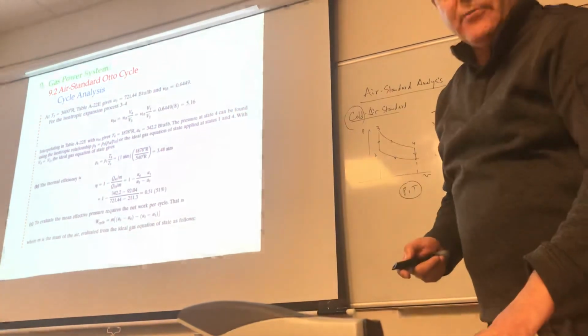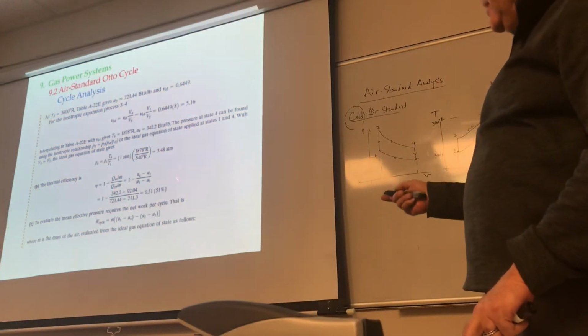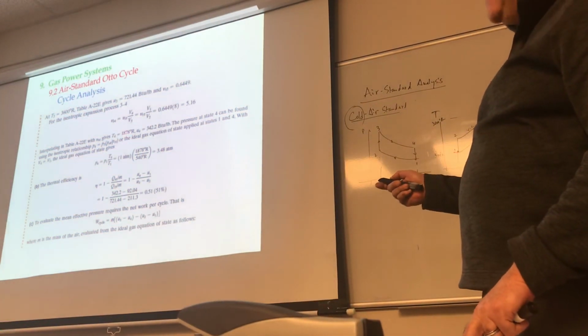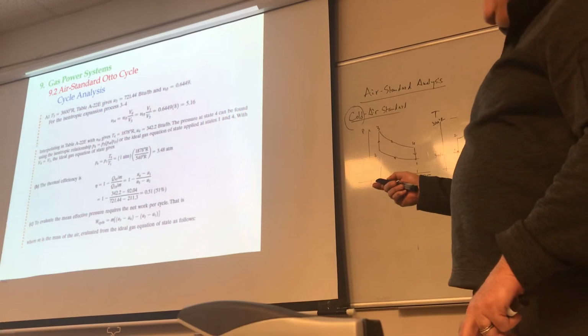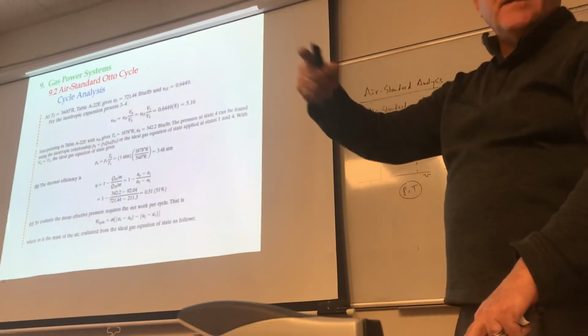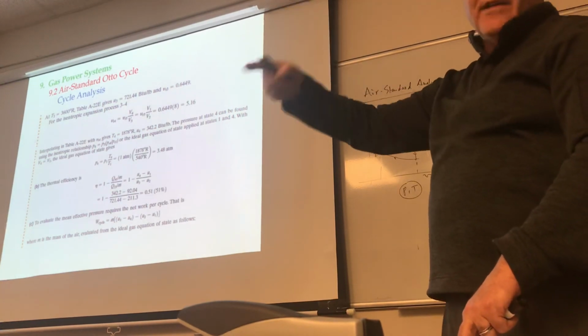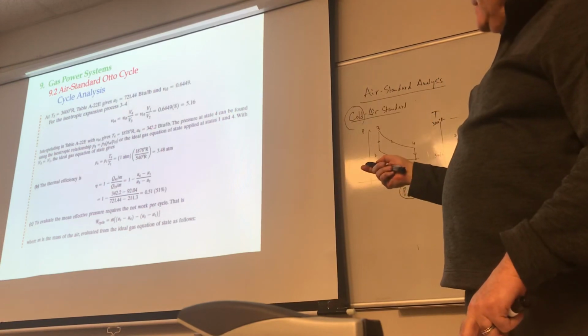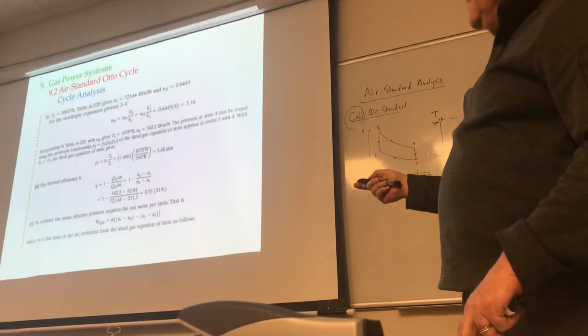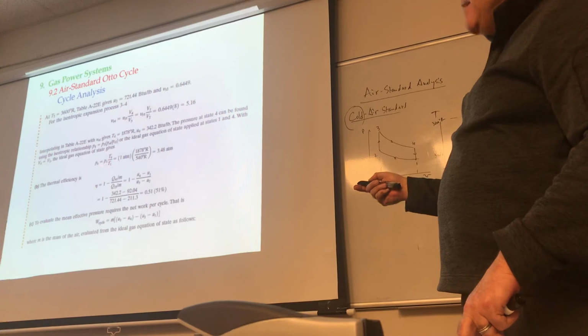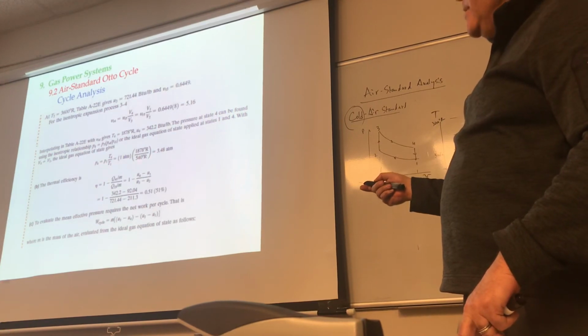1850 or 1900, yes. So you have to do an interpolation, and it happens to be 1878, and the same idea. It's the same repeating, boring stuff that you'll be doing. You find a U4, and then find what the pressure is again, because it's the same volume, right? P4 over P1 is the same thing as T4 over T1.